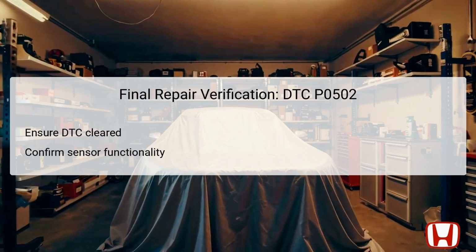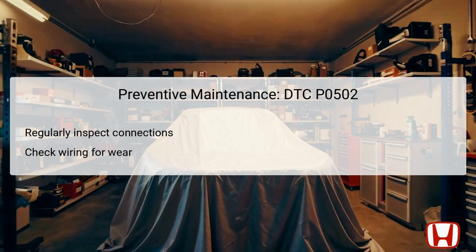If the repair methods effectively restored function without further issues, the vehicle should now perform optimally. This final step serves to validate the success of the troubleshooting and repair process. Preventive maintenance is essential for maintaining the integrity of the CVT system and minimizing the risk of DTC P0502 recurring. Regular inspections of electrical connections and wiring should be performed to identify any signs of wear, corrosion, or poor connections. These preventative actions make it possible to catch issues before they escalate into significant faults causing system disruptions.